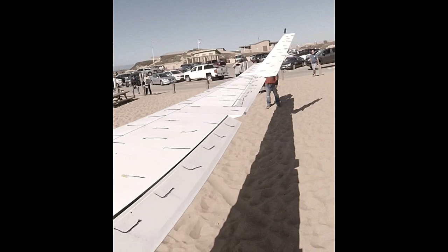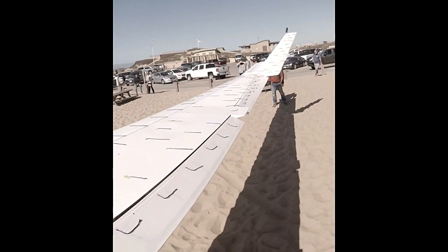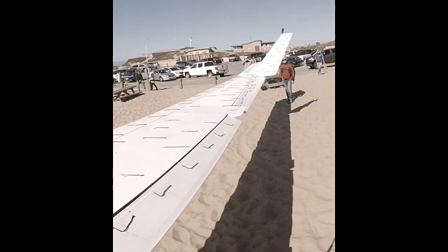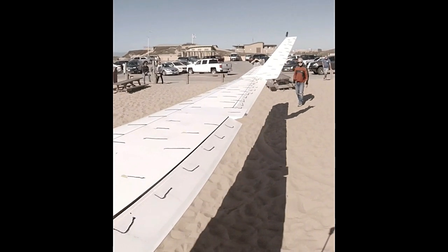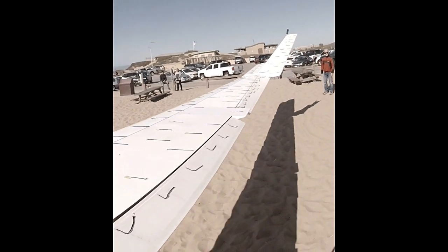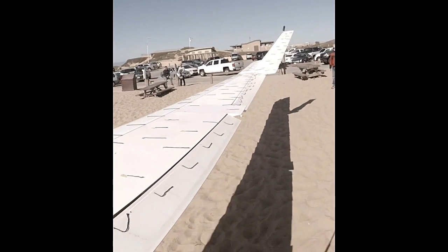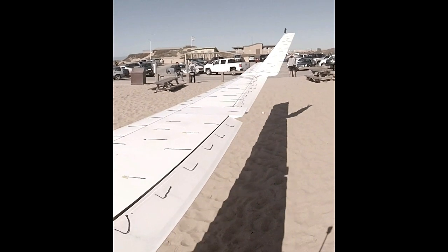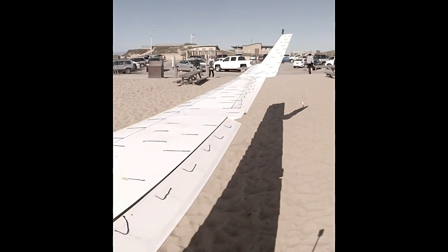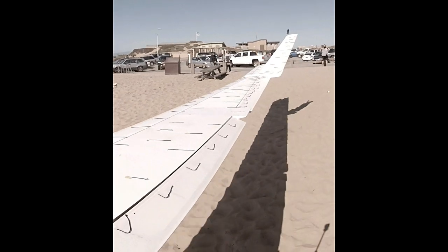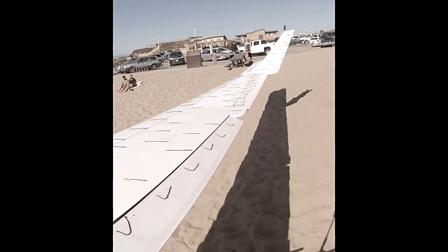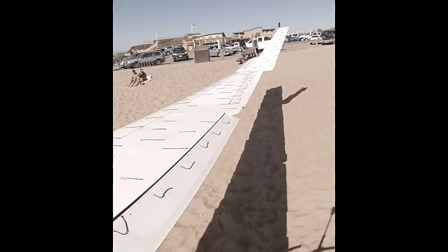This is the right wing, same flight, and you see a lot of spanwise flow on that down elevon. A lot of spanwise flow on the flap. It's experiencing the same type of conditions as that low speed, low Reynolds number flow tries to go around the corner. It can't. Runs into the adverse pressure gradient and just goes out spanwise. Not a great thing on the flap, but not something that would cause me any undue problems because the same thing's happening on the other side. So the extra drag that it's creating is symmetrical.